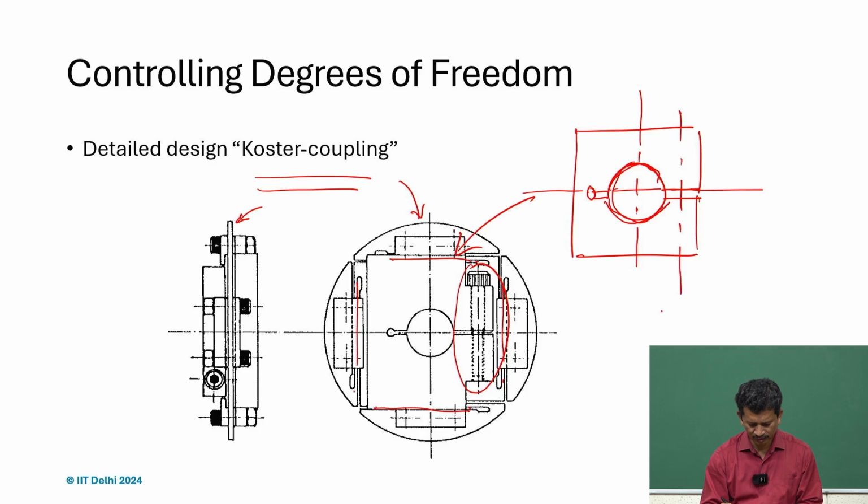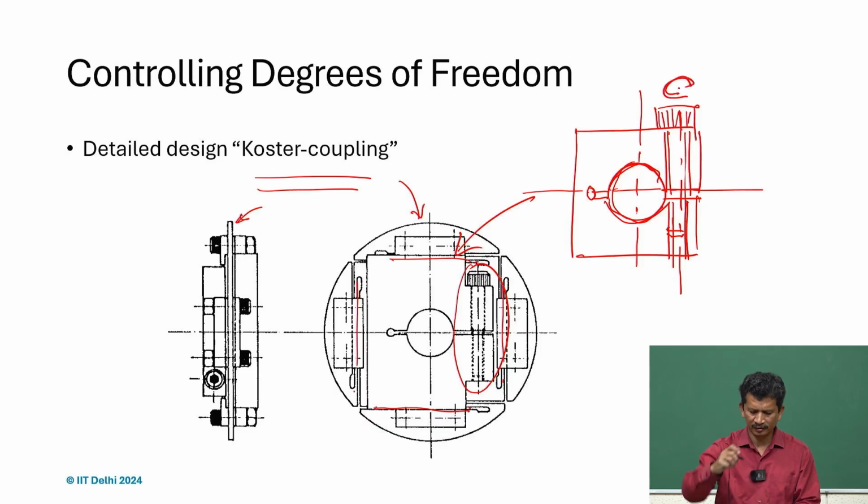We can have a threaded hole here and a clearance hole there, and then put a screw in and tighten it. The moment we tighten it, this closes, and this thin section is very important because it allows the bending to happen. These two parts just bend, and as you tighten, it clamps the surface, so you will not damage the surface of the shaft.